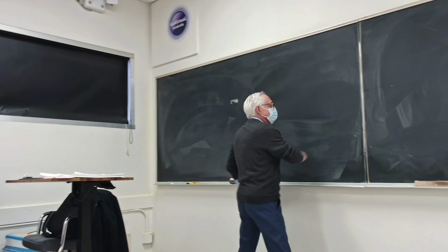Okay. For nozzles and diffusers, therefore, I see that W dot of the control volume is 0. There is no shaft here. And at steady state, what do we have therefore? Rate of change of mass of the control volume with time is 0. Also, dE control volume with time is 0. Right?